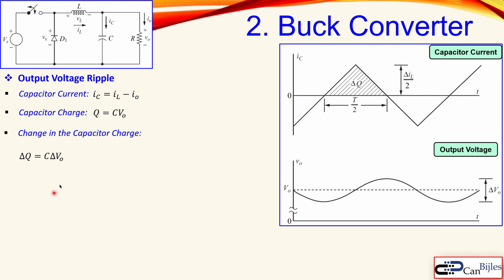This is now the expression, and you see here the expression for our peak output voltage. Using this graph, and since we know that the average capacitor current is 0, so this is leveled at 0, this triangle area is where the charge is. So we can calculate what that is. This is really geometry.